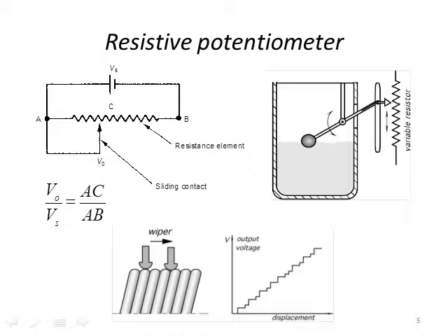And then in the upper left-hand picture, you can see that the measurement voltage that we measure is then a function of AC over AB multiplied by the potential that you apply to the sensor. So the output is then going to just be a function of how the wiper arm moves, as we know with potentiometers already from our high school days doing simple electronics.